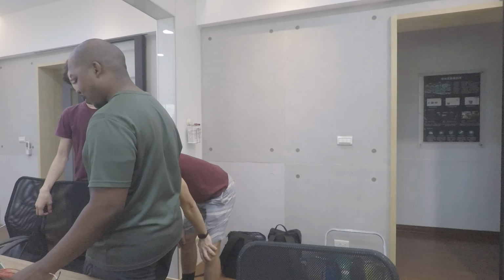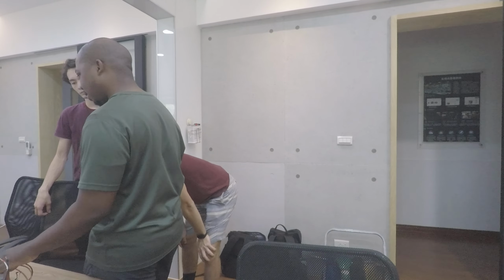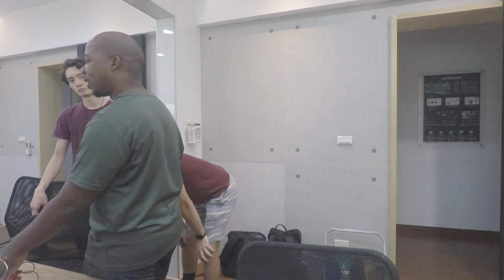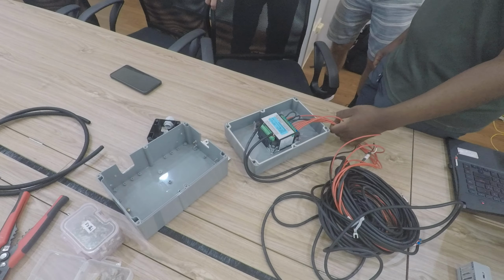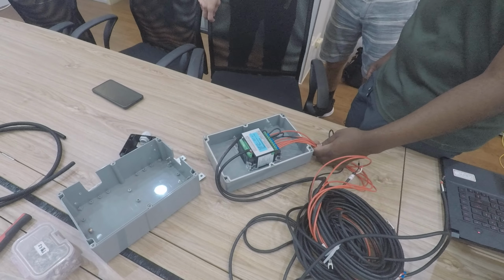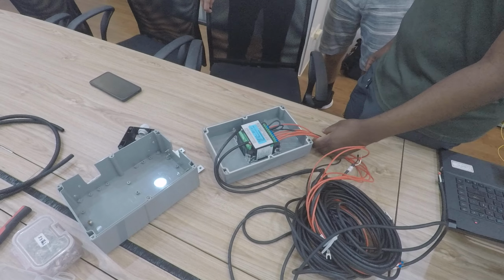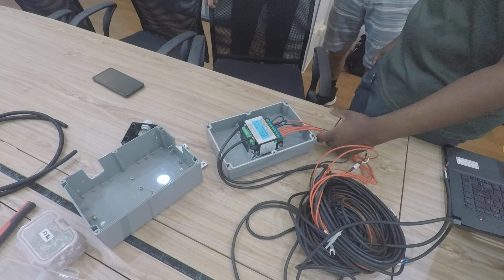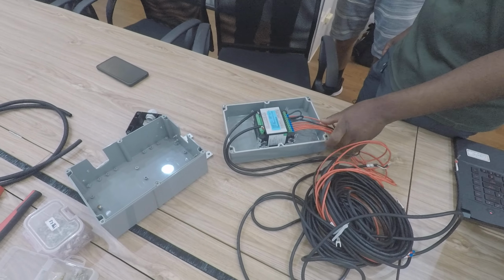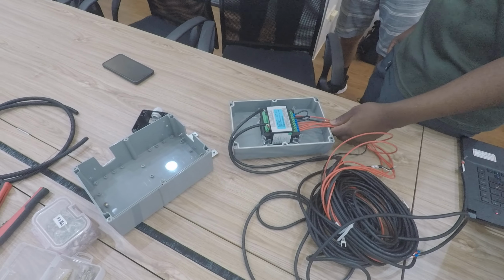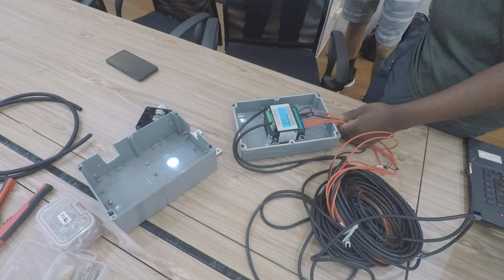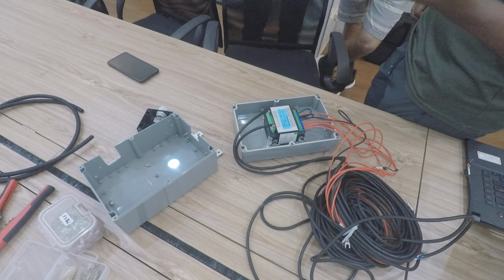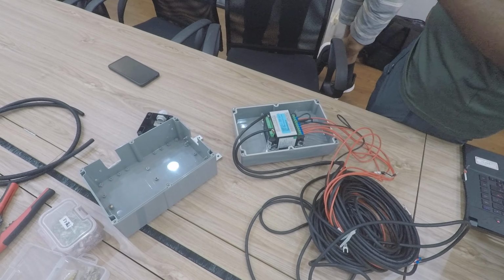So silicone is, okay, how to explain silicone? There are different types of insulation: we have PVC, and silicone is another. Depending on your use and environment, you need to be mindful of what kind of wires you use. For example, if your wires are going to be exposed to sunlight, I would not suggest using PVC. Do you know why?